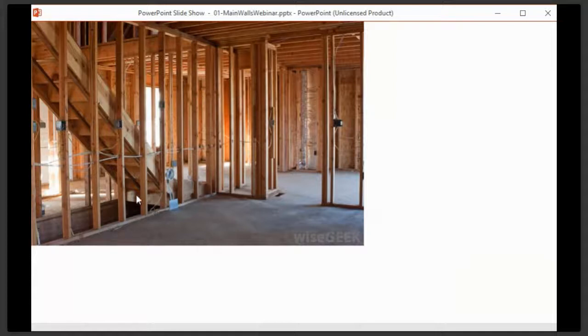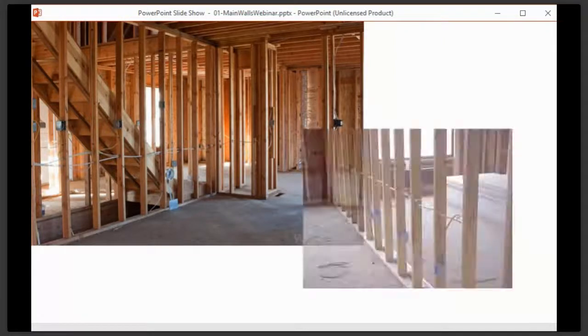And the beauty about this is that you can see there's a thickness here. There's a depth to the wall. And on either side, you'll apply plasterboard. This gives a cavity within the wall, and that's where we can hide all our services. So here, this is electrical wiring. You can see that we've got the basics of electrics in there. And you cannot do that with a solid construction wall. Either you have to channel out a part of the wall, or you have to fix them to the surface. It's going to be one or the other.